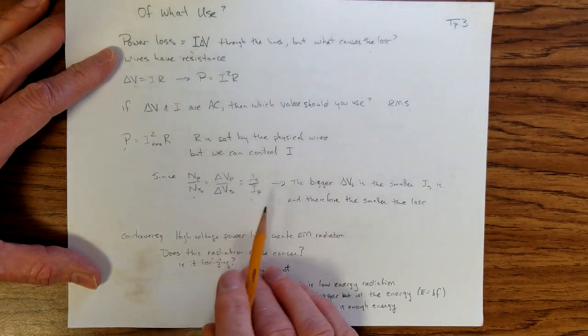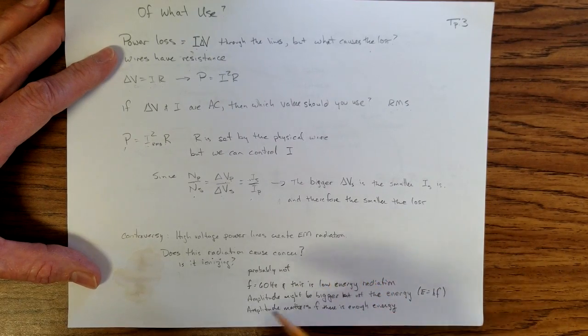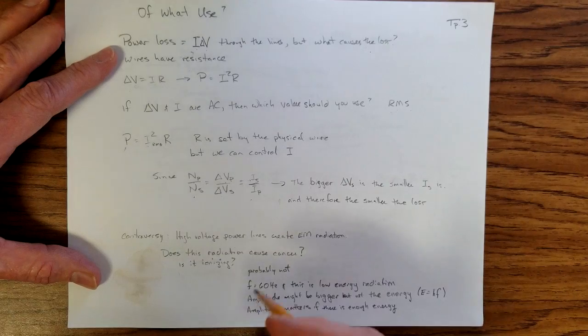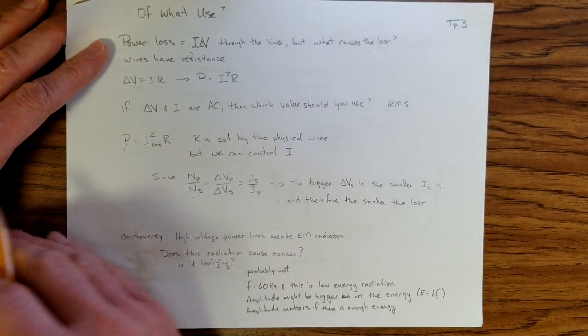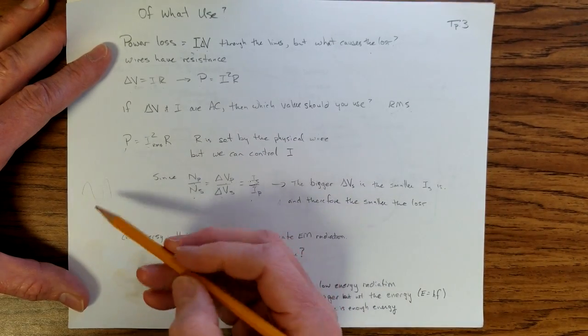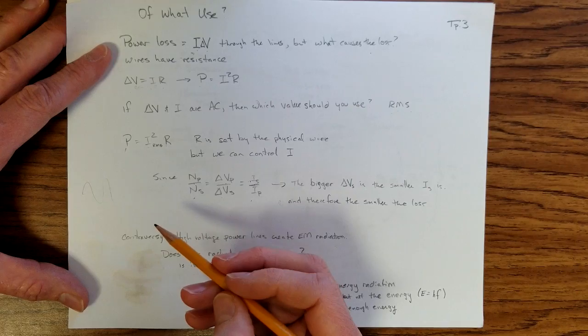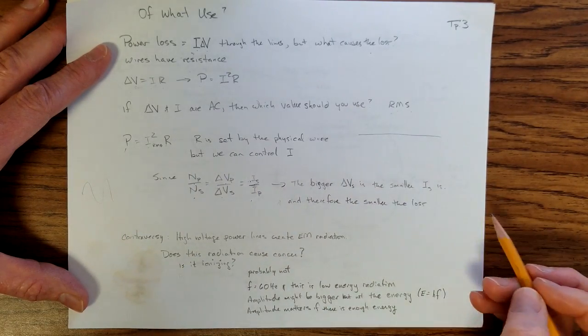And so this gives us a way of really cranking up the voltage in order to reduce the current, in order to have less loss. And with DC, because it is only in one direction, it's a lot more difficult to do that. Alternating current is moving back and forth. We have a continual changing of voltage, whereas DC, at least when it was first being discovered, was basically flatlined.